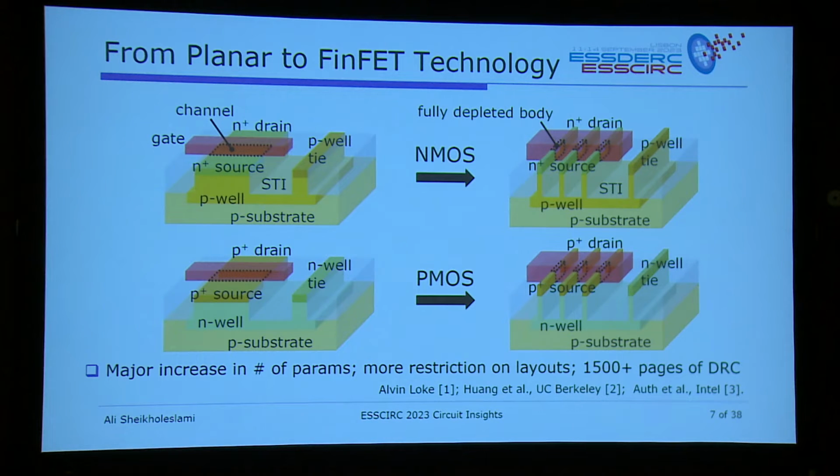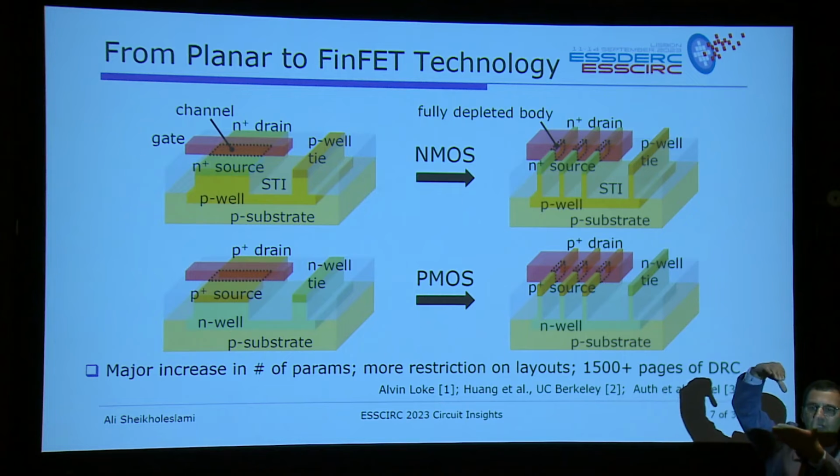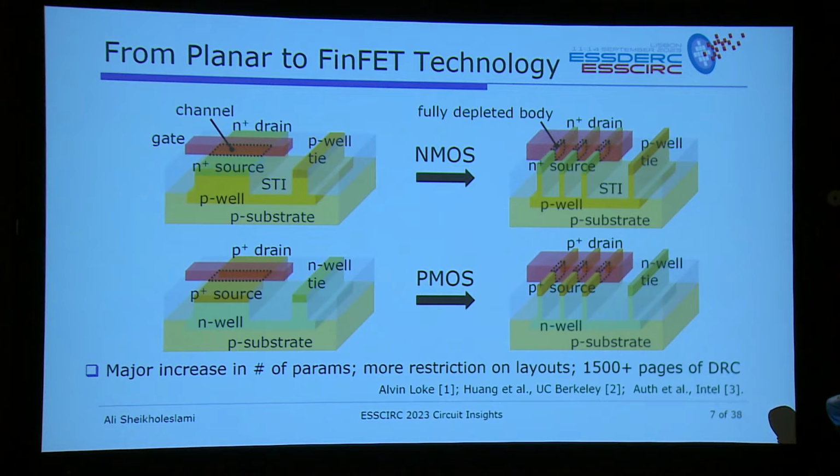And then it could go, in the last few years, to FinFET. And you remember we talked about controlling electrons? When you're controlling electrons using a planar transistor, you just have a gate that is sitting on top of silicon diffusion, and is controlling electrons that are moving underneath. But then we felt that's not enough control, right? This is not enough control. What we should do is we should go and surround the area of diffusion so you have better control.